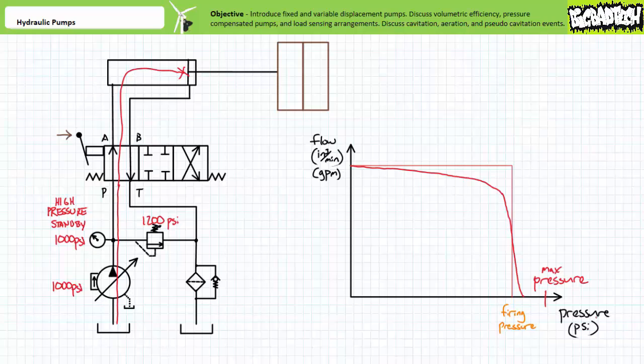Notice at pressures close to the firing pressure, the pressure-compensated variable displacement pump still produces a tiny amount of flow. This flow is intended to take the place of any liquid loss due to leakage and maintain consistent pressure, all without the necessity of actuating the relief valve. This is equivalent to easing your car into a parking space after a long journey rather than just slamming it in there at 60 miles per hour like some amped up meathead.